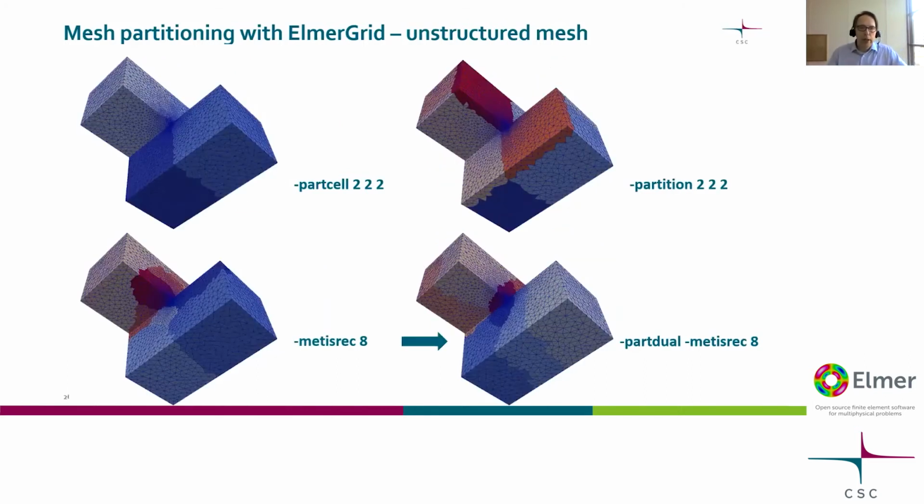On the other hand, if we have an unstructured mesh, which has no regularity in the graph, then certainly this one, for instance, is not good at all. It's really bad. So I would bet this is the best among these. So know your mesh, and only use the geometric one if you have a very regular, simple mesh.